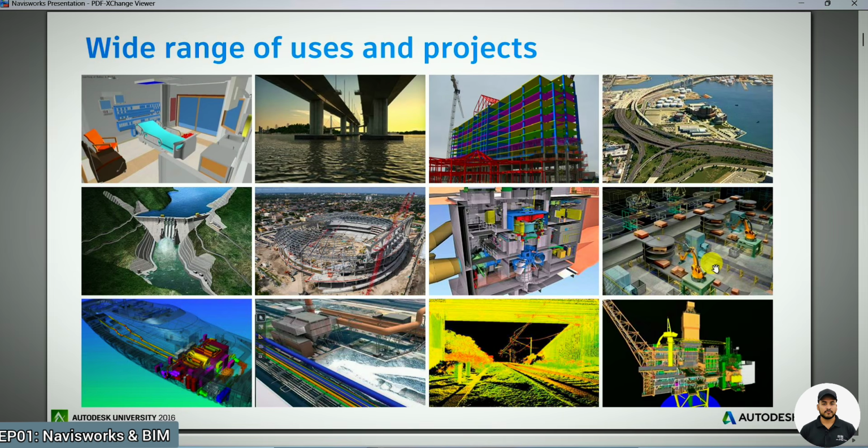Once all those subcontractors start creating 3D models and updating regularly, weekly or monthly, for coordination, we will require all those NWC or NWD files in one Navisworks software. We have to open all those NWC and NWD files from the different contractors, and do the design review, or any clash detection, or if we want to extract the BOQ, then all those features we can access in Navisworks. So basically it will be helpful in BIM for good model coordination and for data extraction, or the parameters if you need to extract.